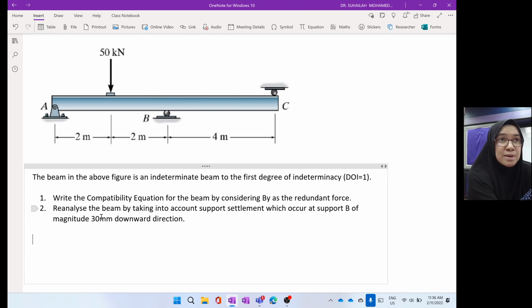Displacement. So from that we know that we need to have displacement, then only we can get the redundant. Okay, displacement. There are two displacements. One is delta B naught. One is FBB. Clear that one? Okay, we will have two displacements, delta B naught and FBB.